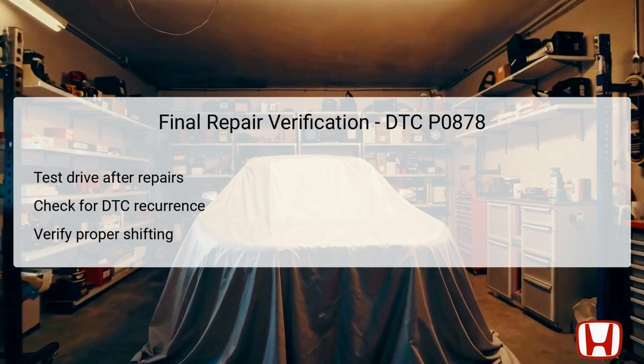Once repairs associated with DTC P0878 have been completed, it is vital to conduct a final repair verification to ensure successful resolution. After addressing any faulty components, be it the fluid pressure switch or wiring issues, perform a comprehensive test drive of the vehicle. Pay close attention to the shifting behavior, confirming that the transmission smoothly transitions through all gears. Post-drive, utilize the HDS to check for the recurrence of any DTC codes. The absence of codes confirms the effectiveness of the repairs made.